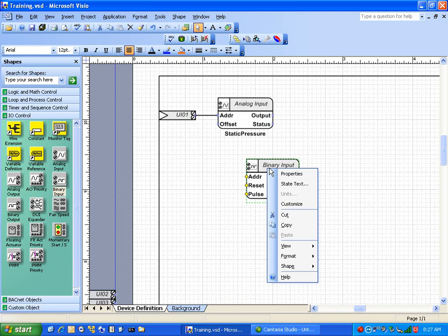Sometimes I leave those ones alone, and I wait until the system is actually started up and running. If everything's running normal and I see what its value is, that's when I'll go in and change it at the graphic level to say, okay, this value is on and everything's running just fine, so I'll make on normal and off will be alarm in that case. But that's only like one time out of ten.